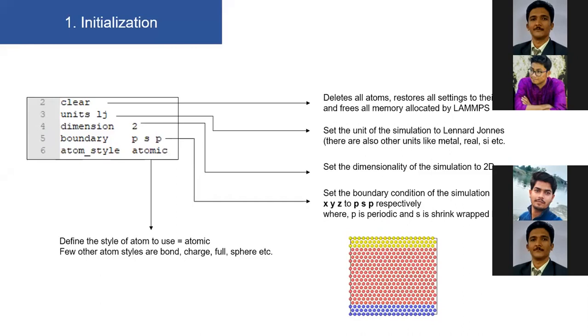I think you know about periodic boundary condition, that suppose this is an atom, then the same atom will be repeated throughout the simulation in the same position. I mean, suppose this is our total unit, the total simulation box. So this simulation box will be expanded throughout the space in the same way. So the way it reacts, the other boxes will react the same. So you don't have to calculate a large box. Rather, if you calculate a specific section, then it will already be calculated.